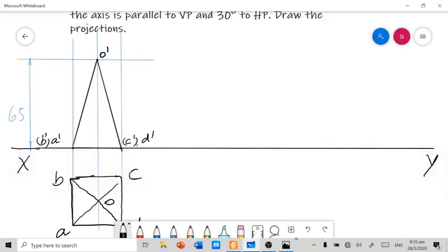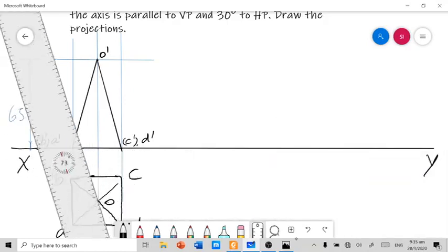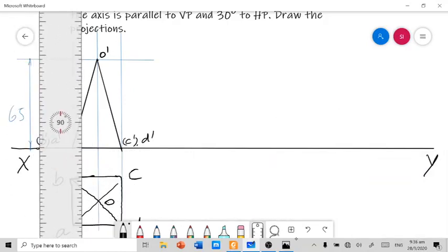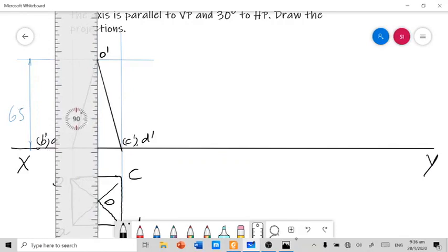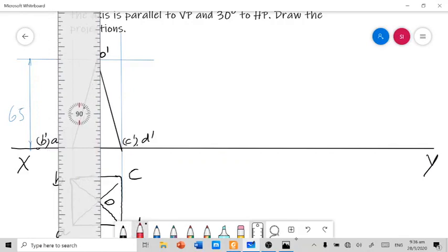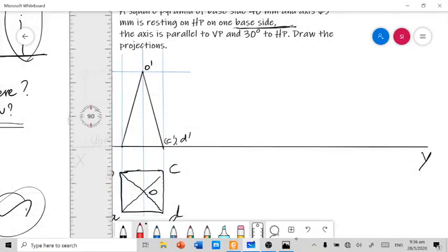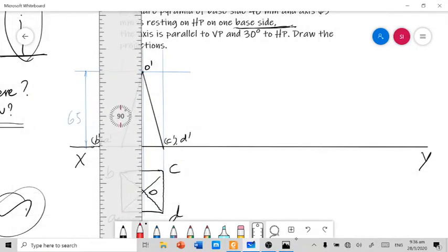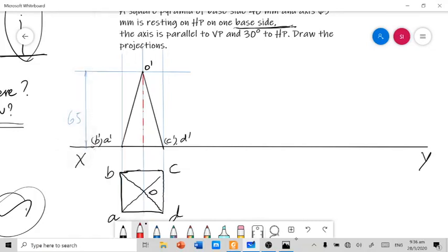This is nothing but your lateral view of the solid, and in the meantime you need to draw the axis of the solid also, in the proper line format of the axis. You need to draw the axis. The axis line should be retained within the lateral view of the solid. It should not exceed top and bottom. Okay, so this is nothing but your lateral view of the solid.